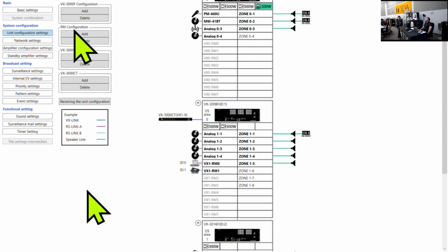I see. The frame itself doesn't have the capacity to push the configuration. The software on your PC has. So once you bring the new frame, of course they need to do the DIP switches stuff, ID and IP address, and then push the configuration from the software to the system, because the frame itself is empty. When you connect to the network, other frames don't know there is a new frame in the network, and this new frame is empty, so it doesn't have anything inside. This is what we were getting at.